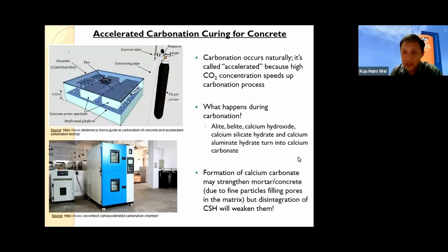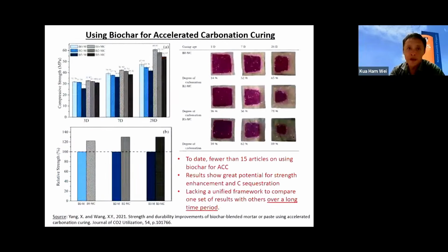And the reason is that the formation of calcium carbonate may have occurred at the expense of calcium silicate hydrate, which we all know is the glue that holds all the particles in concrete together.